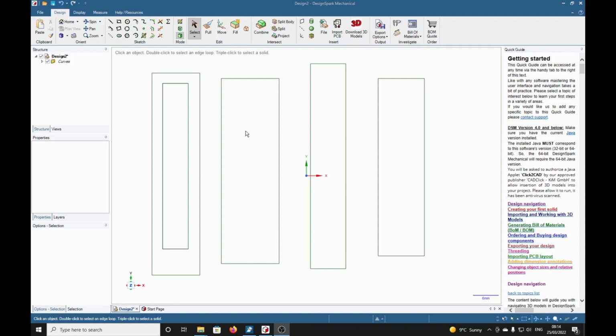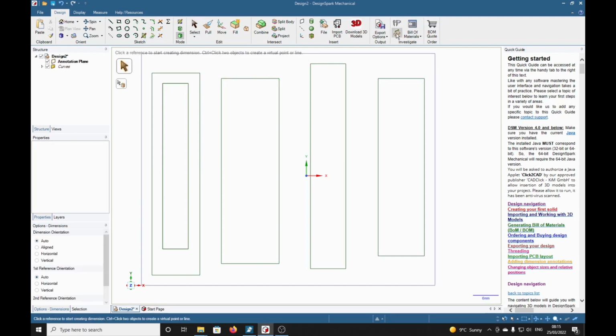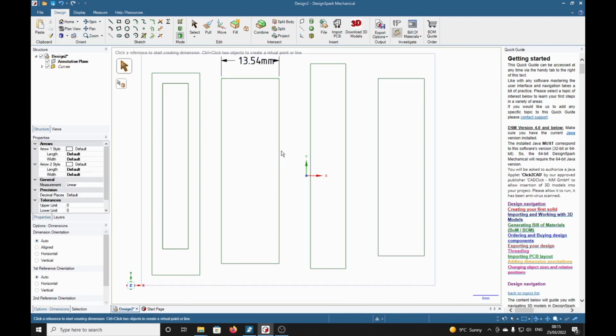Now I'm going to put another rectangle in the middle of this rectangle here, which is going to be precisely in the center. So in order to do that with this technique, I'll need to know the dimensions of the big rectangle. So I'm going to select the dimension tool. That puts an annotation playing around the whole lot. And now I can put a dimension on the width, select the edge, click and drag on the height.